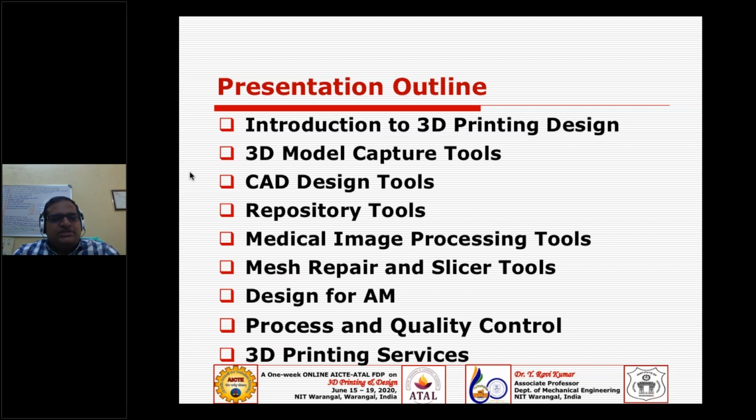During session 2, we have learned that there are a lot of problems with the STL file formats. Say you have triangles which are missed or misplaced, or normals that got flipped, or triangles that got overlapped. So many, or some kind of degeneracy towards geometry or towards topology. So you have several issues with the STL files. So then how to correct them? In order to correct them, as we know, STL is basically a mesh file.